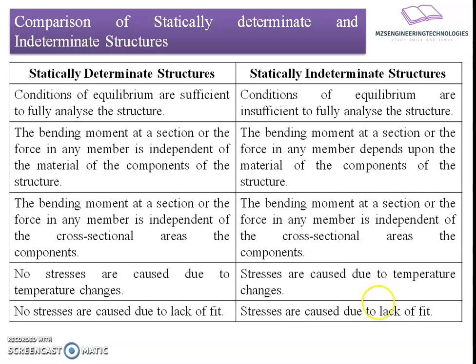nearly all the degrees of freedom are locked, and in the locked degrees of freedom, the member will be subjected to either compression or tension due to an increase in temperature, or due to a stretch or pull applied to get proper fitting in the case of a too short member. In the case of a too long member, the member will be subjected to additional compressive forces. Thereby additional forces develop in the member,